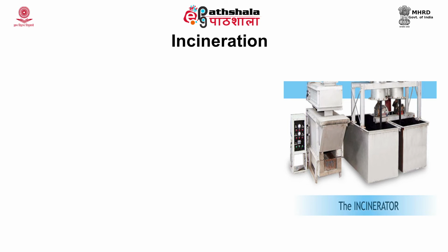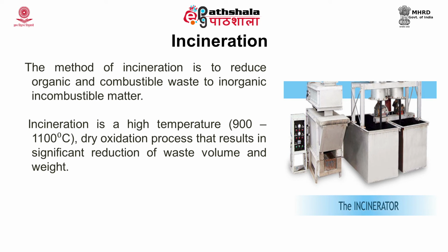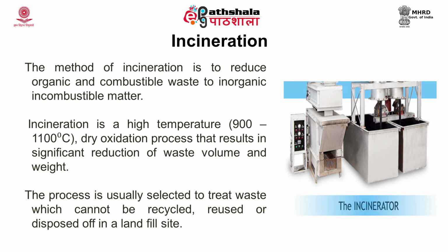Incineration is one important treatment method in the management of biomedical waste. The method of incineration is to reduce organic and combustible waste to inorganic, incombustible matter. Incineration is done at a high temperature of about 900 to 1100 degrees Celsius. It is a dry oxidation process that results in significant reduction of waste volume and weight. The process is usually selected to treat waste which cannot be recycled, reused or disposed of in a landfill site.